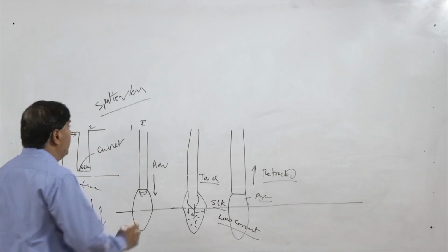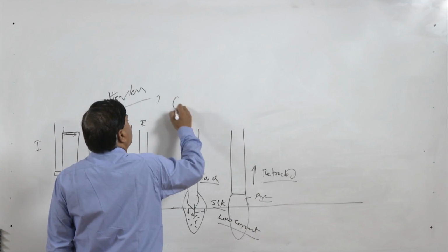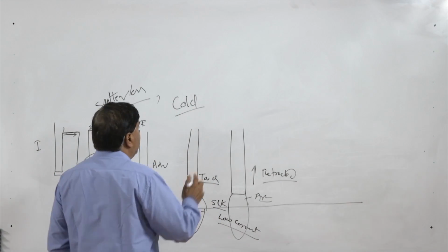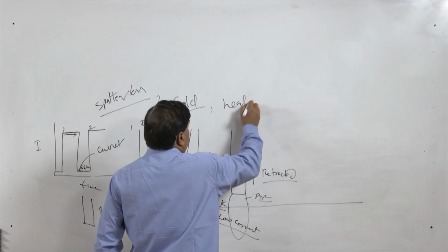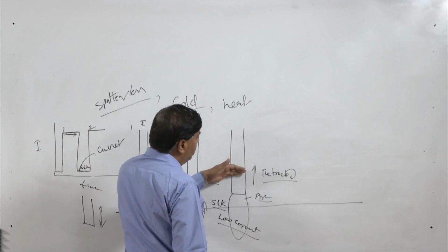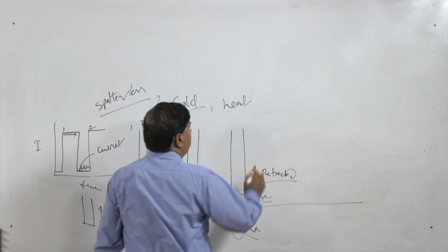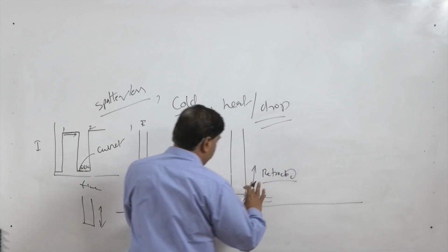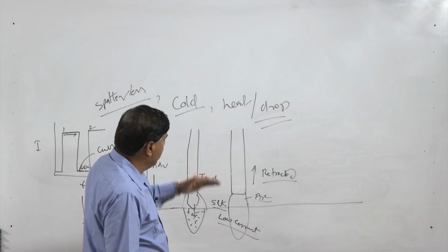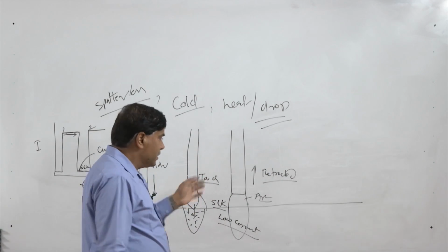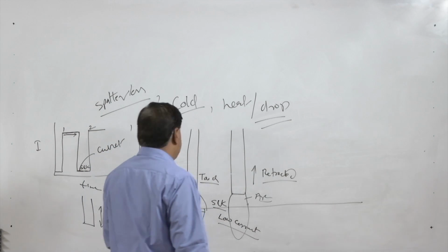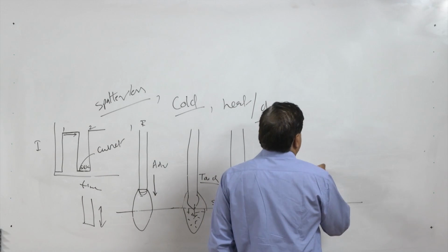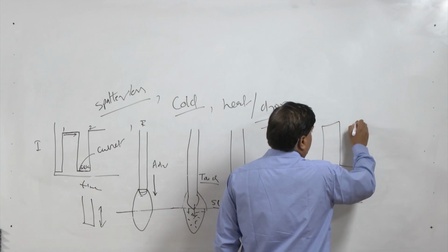is very low. So, here you can say it is a very cold kind of situation, no heat generation. Whenever there is heat generation, the electrode is away from the pool, and the peak current helps to develop the heat, and so the drop is formed. Once a drop of large enough size is formed, again the electrode advances. This sequence is normally repeated, and it is synchronized according to the pulses between the peak and the background current level.